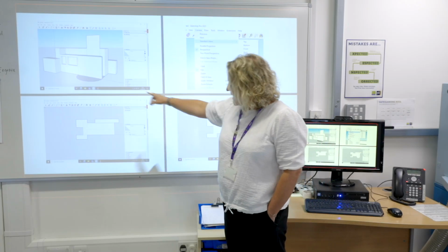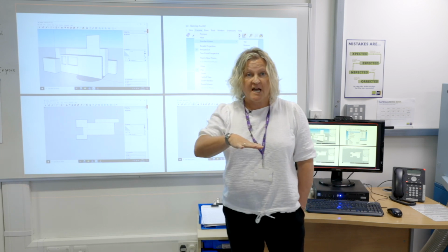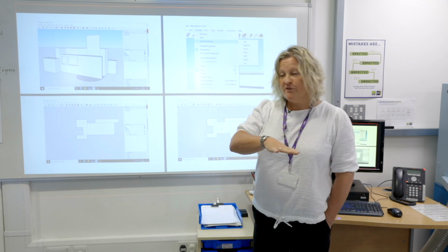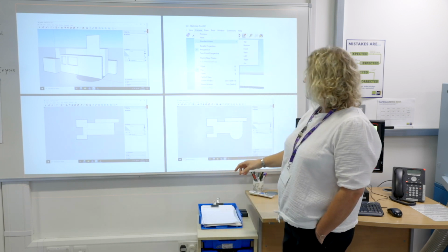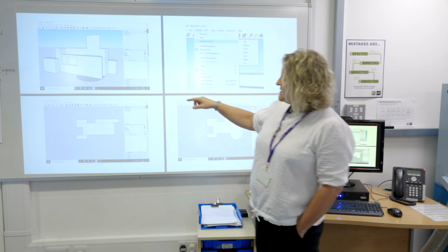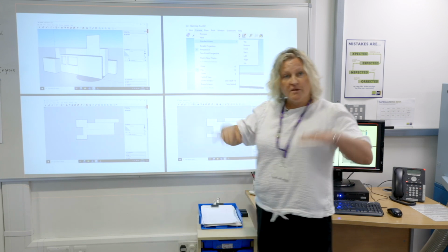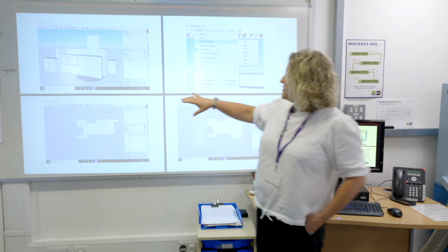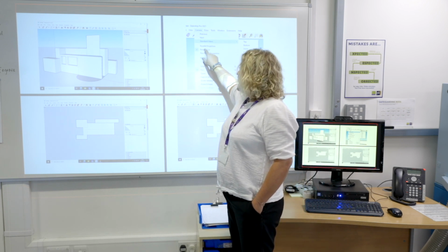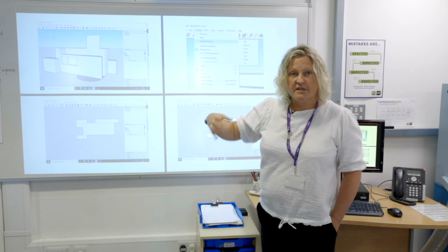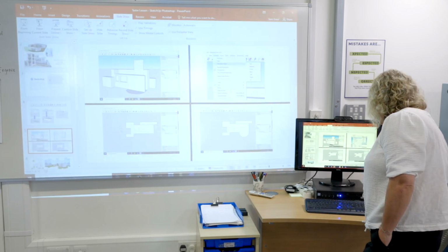From this screen here, what you will see is I've just done lots of rectangles, and I've done this as a plan view to start with. So I know that they're all together, laying over each other, and then I've just extruded certain sections into this building. One of the benefits of doing this is you can see where they are and where you're pulling them to. I would always do it as a plan view, and I'd also always do it as parallel projection, and only go back into perspective once you want to look at this as a final image.